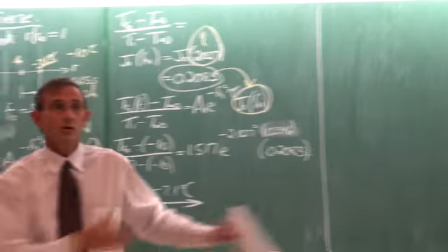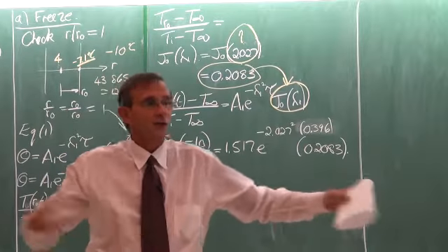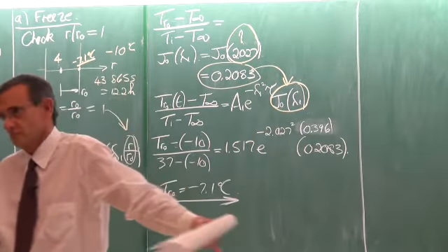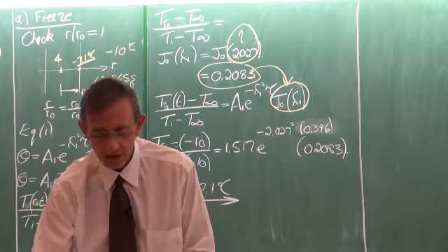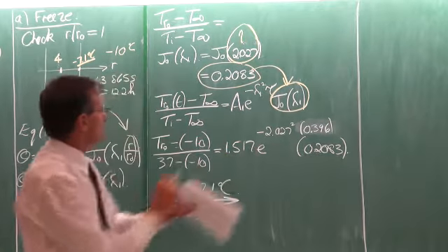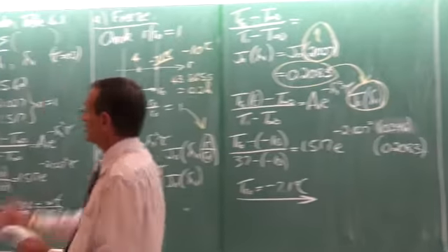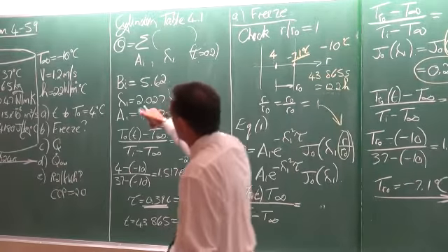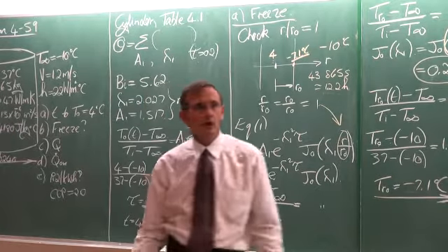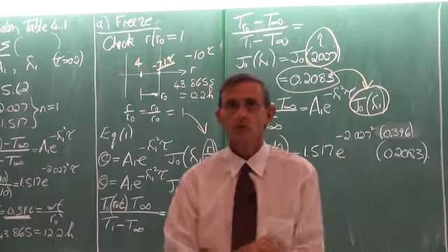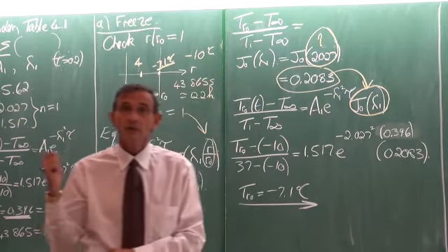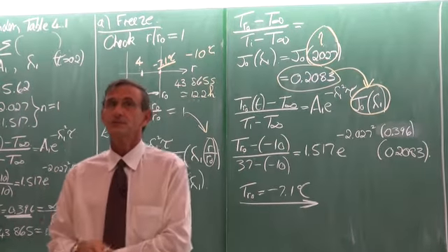So the conclusion that can be made is the outer part of the carcass will freeze, which is not good. So the design of this refrigeration system needs to be changed. Maybe the velocity is too high, or the temperature might be too low. Right. Are you with me? Any questions, ladies and gentlemen?